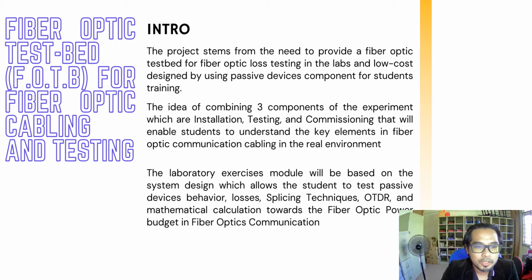For the intro, the project stems from the need to provide a fiber optic test bed for fiber optic loss testing in the labs, and a low cost design using passive device components for student training. The idea of combining three components of the experiment, which are installation, testing and commissioning, will enable students to understand the key elements in fiber optic communication cabling in the real environment.